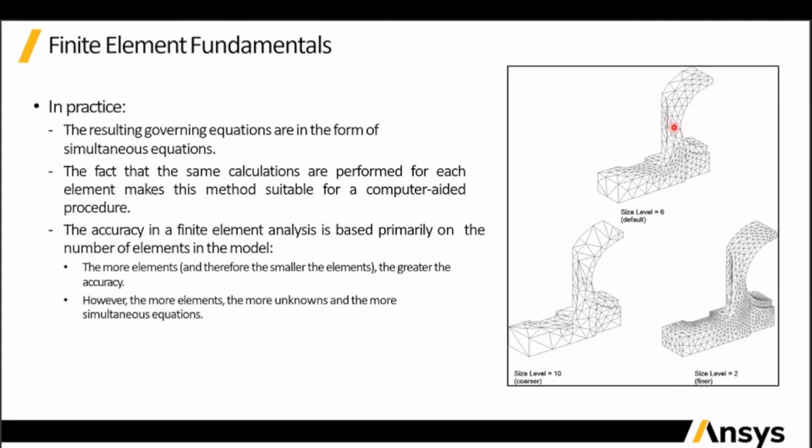Similarly, if you are working on any finite element analysis, the way to improve the accuracy of your FEA model is by adding more elements. The more elements, and therefore the smaller the elements, the greater the accuracy, so that the maximum area is covered. However, the more elements, the more unknowns and the more simultaneous equations there will be.